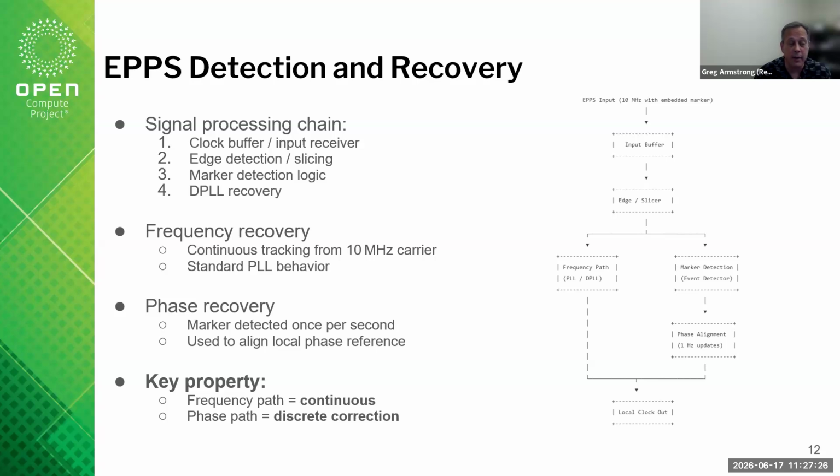Well, the nice thing about 1 hertz is it's pretty much a common multiple to every clock you generate, right? There's maybe a handful that might be half a hertz or whatever, but fundamentally, most of them are at least 1 hertz multiple because 1 is a common multiple of pretty much every full integer clock you make. And most of the time, we're dealing with clocks that are in the megahertz, and they don't typically have more than 6 decimals of resolution, right?